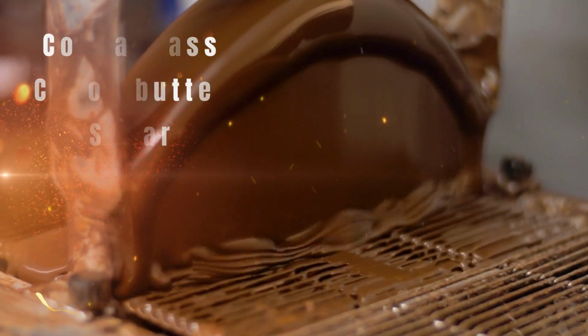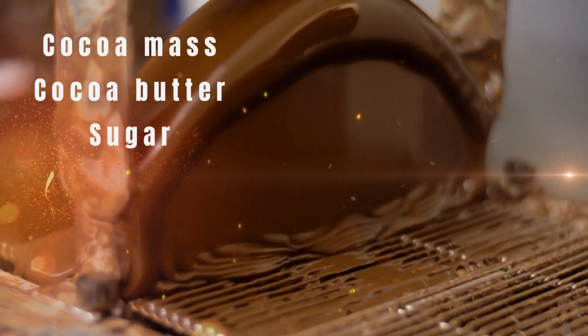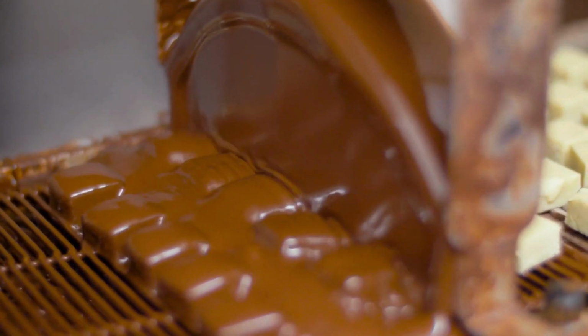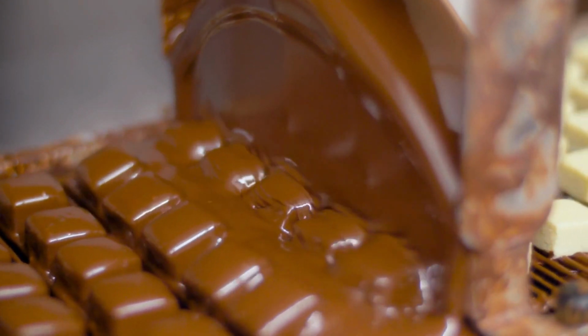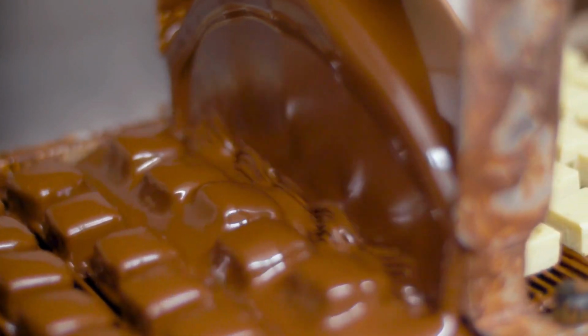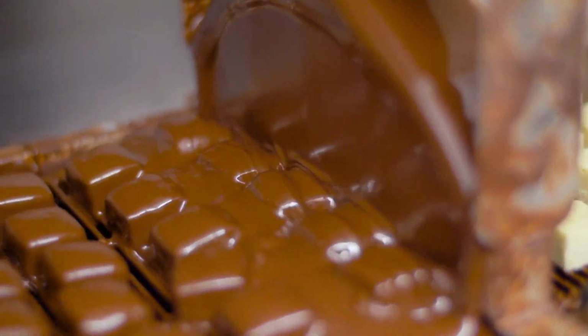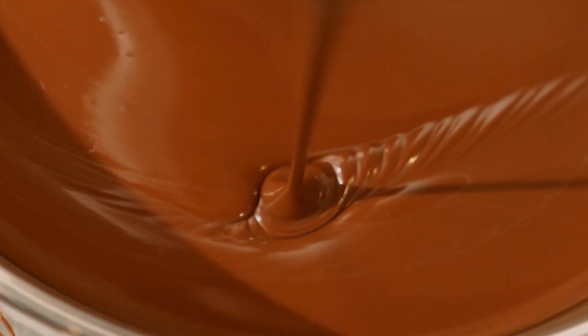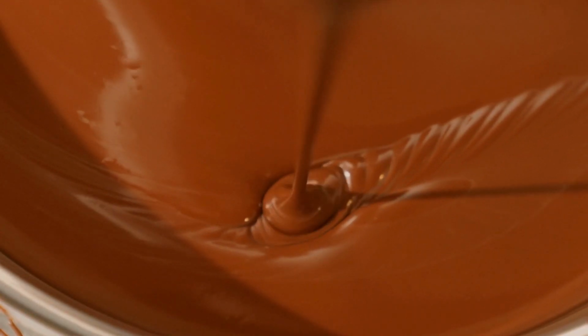Refining is the next step, where the chocolate mixture, cocoa mass, cocoa butter, and sugar, is passed through a series of rollers to refine the particle size, typically reducing it to around 20 microns. This process is critical for achieving a smooth texture and mouthfeel in the final product.